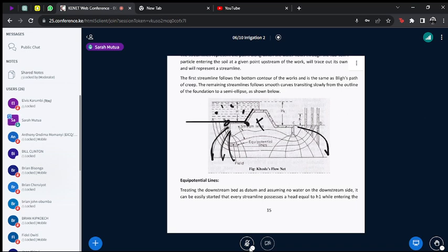Of course, if you take the datum to be mean sea level, the equipotential head at point D will be, you have to add the altitude of that area and also add the altitude in the upstream part. So, for the hydraulic head calculation, you can play around with the gravity term of the Bernoulli equation by setting your own datum. So you notice as the water then flows from the upstream, there's equipotential drop. There is loss of energy. Otherwise, if there was no loss of energy, then there would be no flow of water from the upstream into the downstream.